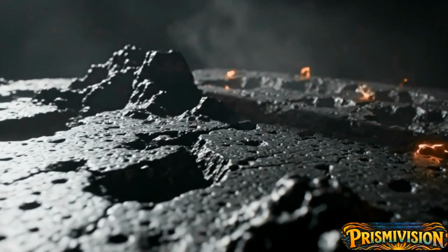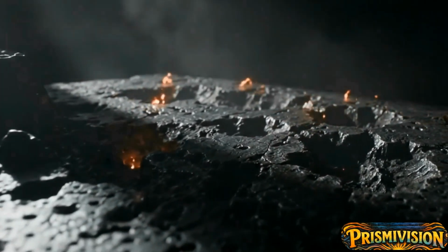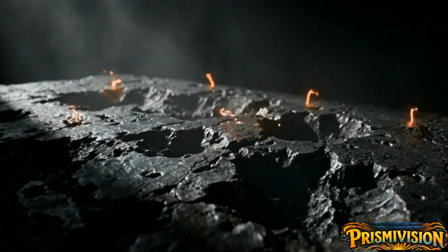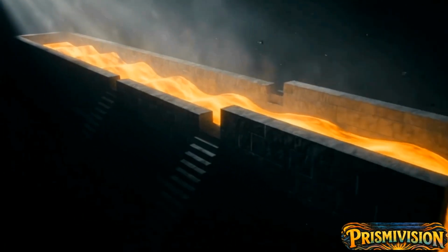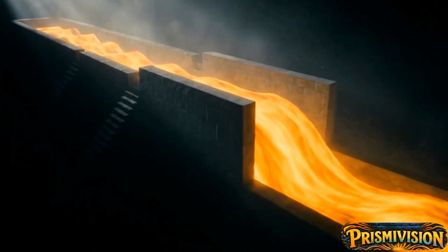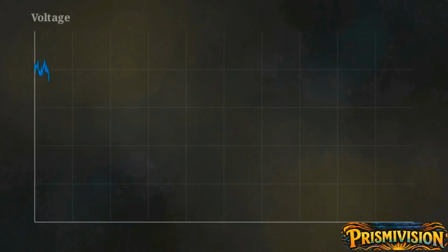Those fragile silicon squares are then embedded into larger ceramic packages with sturdy metal pins, allowing them to interface with the macro world. At this lowest layer, the environment is purely analog. It is plagued by voltage noise, leakage currents, and physical defects that cannot be completely eliminated.